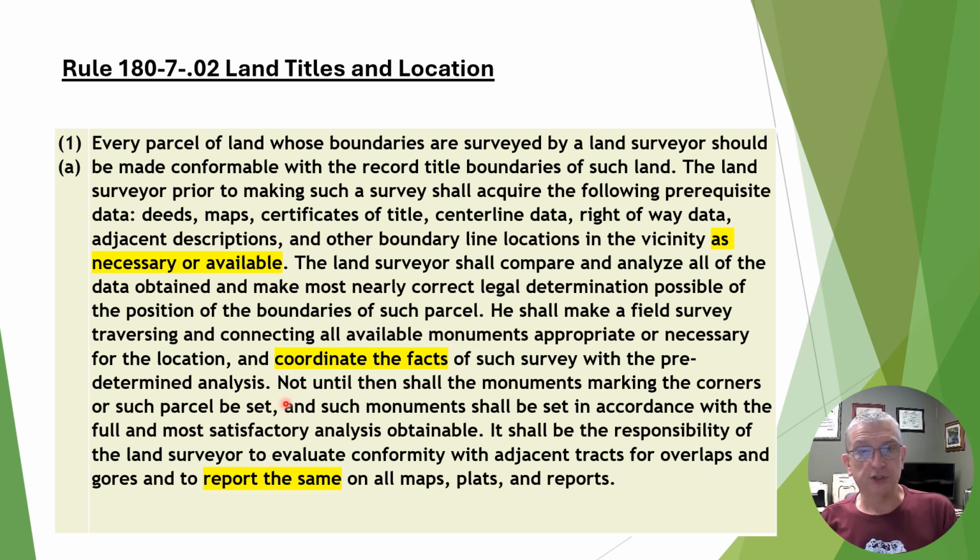Not until then shall the monuments marking the corners of such parcel be set, and such monuments shall be set in accordance with the most full and satisfactory analysis obtainable. It shall be the responsibility of the land surveyor to evaluate conformity with adjacent tracts for overlaps and gores. Look at this highlight, and to report the same on all maps, plats and reports.